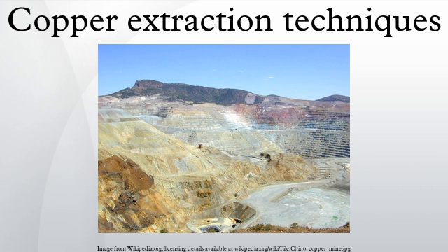At the anode, copper and less noble metals dissolve. More noble metals such as silver, gold, selenium, and tellurium settle to the bottom of the cell as anode slime, which forms a saleable byproduct. Copper ions migrate through the electrolyte to the cathode. At the cathode, copper metal plates out, but less noble constituents such as arsenic and zinc remain in solution unless a higher voltage is used. The reactions are, at the anode, Cu(s) → Cu2+(aq) + 2e−, at the cathode, Cu2+(aq) + 2e− → Cu(s). Copper concentrate and copper marketing.